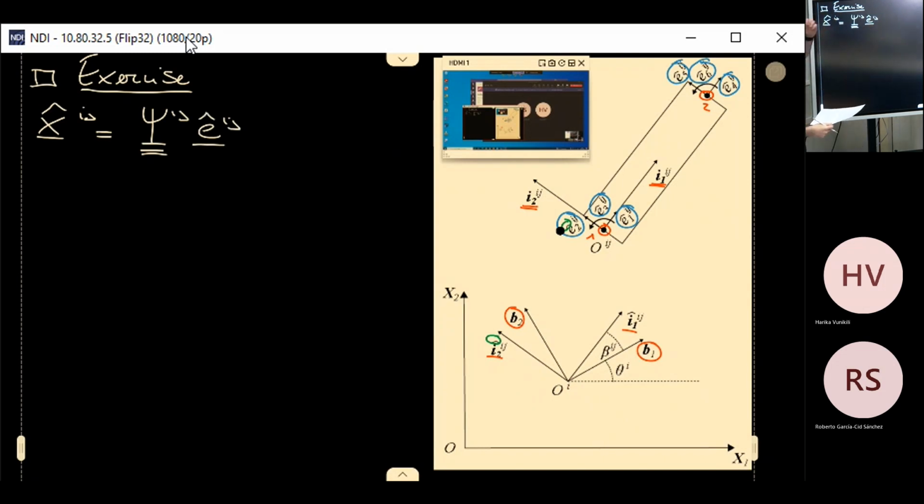So we know that the position within the element of a point within the area, described with respect to the intermediate frame, can be expressed again resorting to the values of the nodal quantities expressed with respect to the intermediate frame, making use of shape functions which are always the same. They do not have to be adapted.